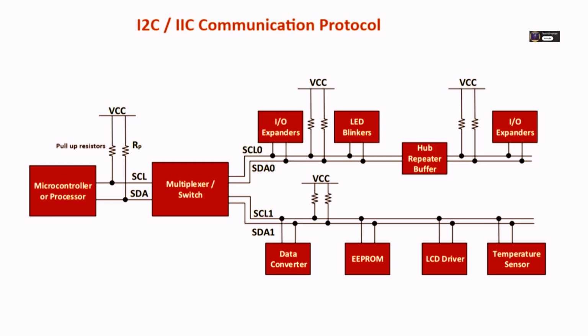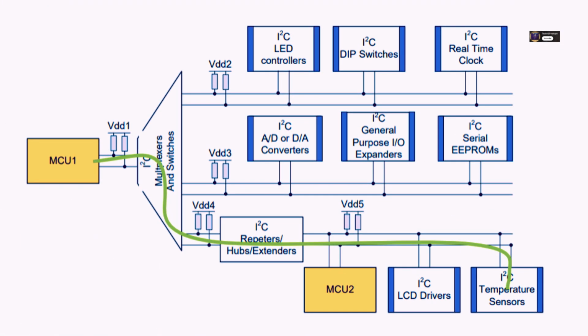So these pull-ups are always trying to pull high, and the chips can only pull low. How does that stop the electrical fights, the conflicts we mentioned, especially with multiple masters? This is the genius part. This open drain plus pull-up design elegantly prevents those conflicts. It makes it impossible for one device to actively drive high while another actively drives low simultaneously. In a normal push-pull output, if that happened, you'd get a direct short circuit from power to ground. Very bad, potentially damaging. Bus contention.